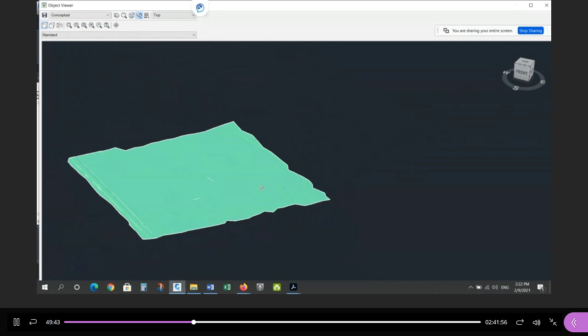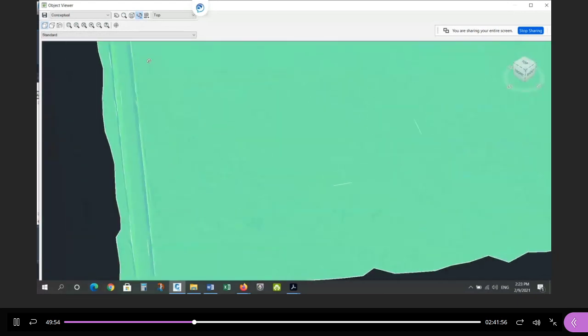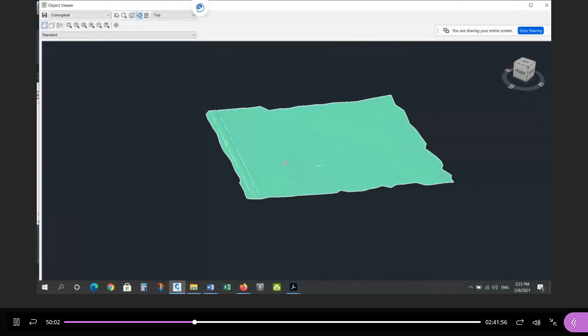Okay. A common error that some people got wrong is they didn't use all the lines for break lines, right? So then the road looks good, but then the ditch looked wrong. All the polylines that should have been used as break lines, not all of them were used. Another common mistake was to use lines that shouldn't be break lines as break lines. So there's a set of lines that should be break lines. Some people didn't use them all. Others had lines that shouldn't be break lines defined as break lines. So too many and not enough was the issue for some people.